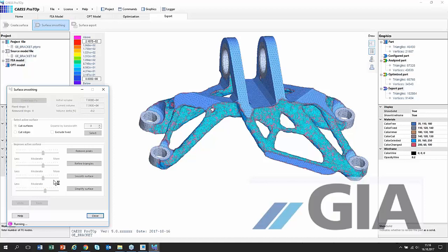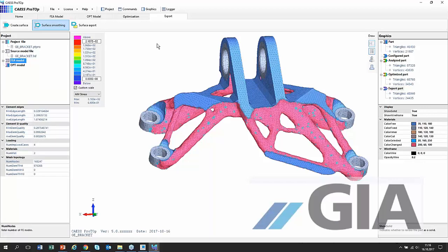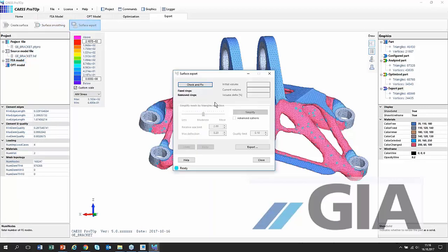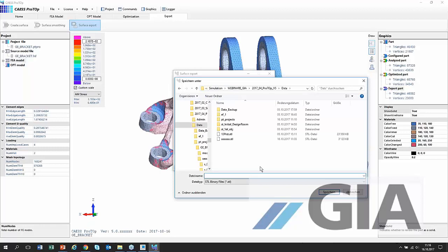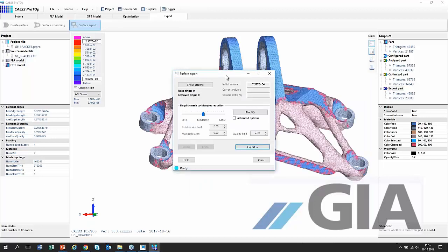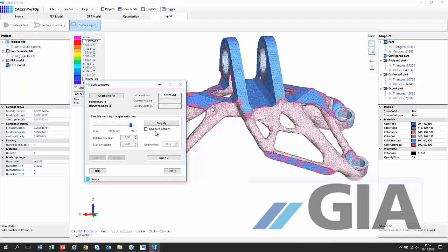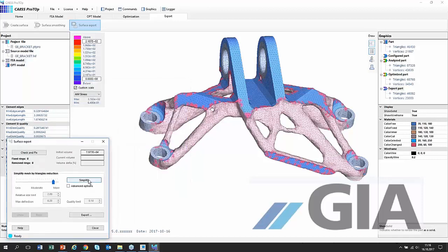This takes a little bit longer. And then doing a little simplification of the surface. And as before, we are going to export the surfaces, and let's do maybe first an STL export. Let's go for my home directory. Let's export an STL file called BBBB, and let's do right now a simplification of this STL file in order to get the Wavefront file, OBJ file.